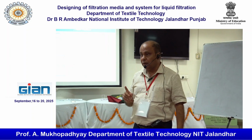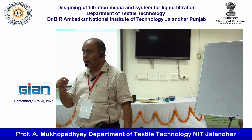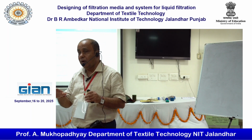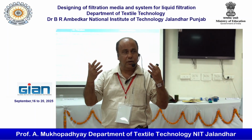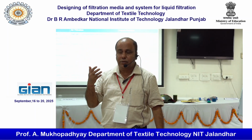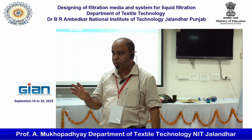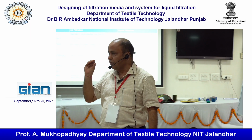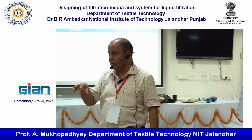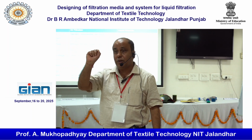That is the point, because we cannot correlate it directly and straight away from the pore size and the particle size. People just try to predict or visualize, and they always try to think in terms of pore size and particle size. It is not so simple. It is not so straightforward. The main thing is that the pore structure in a non-woven is tortuous, and fortunately the very small particles show Brownian motion.